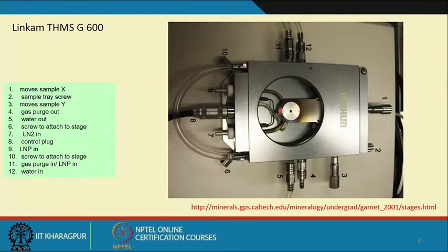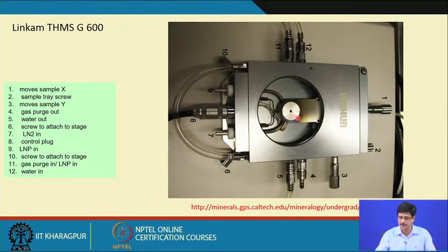The heating is done by the temperature controller, by setting the limits of heating and also the heating rate. This is the silver heating block on which the sample holder, as you can see, is less than about 2 centimeters in diameter, with a central aperture, a central hole for the light to pass through when it is mounted on a transmitted light microscope.